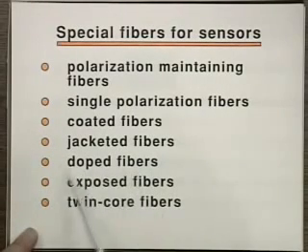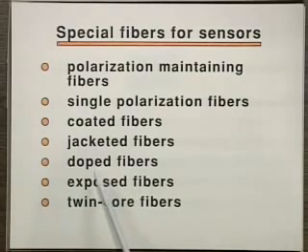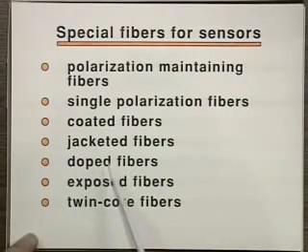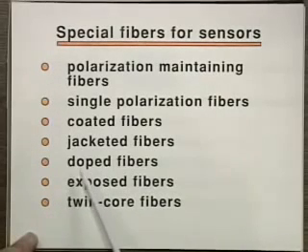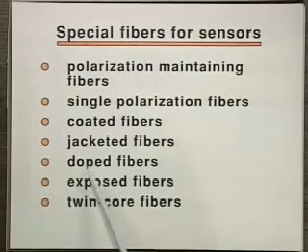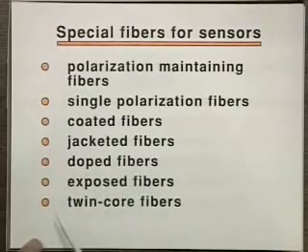Then today it's a big field now, the doping of fibers. For example, if you dope glass fiber with neodymium, and you can pump it with a semiconductor laser, then you can have essentially a neodymium laser, a fiber laser. And you can make them into linear lasers or ring lasers and so on today by doping the fiber.